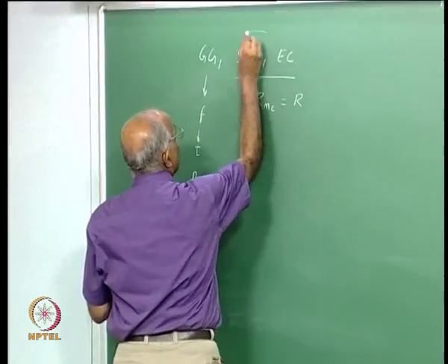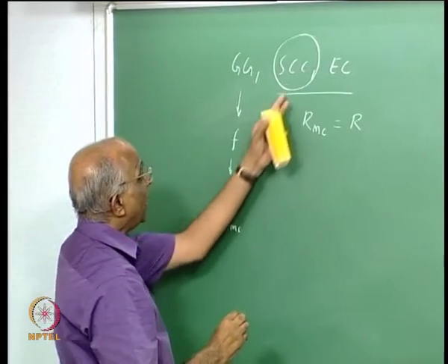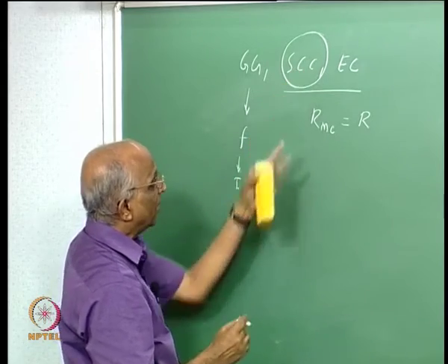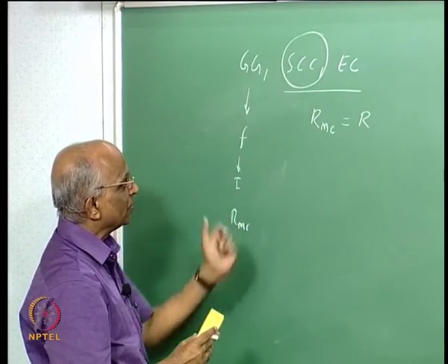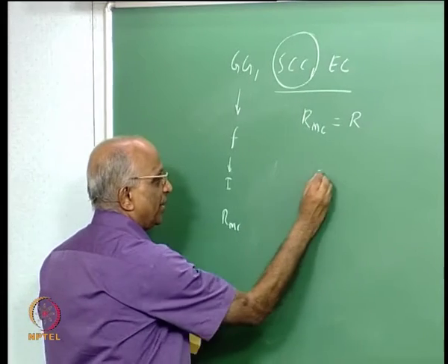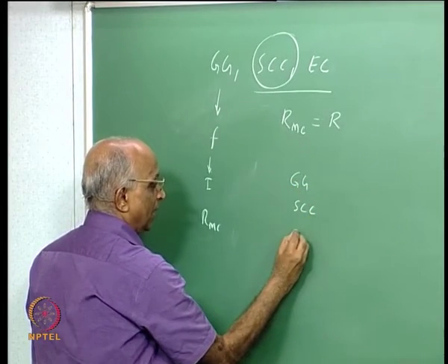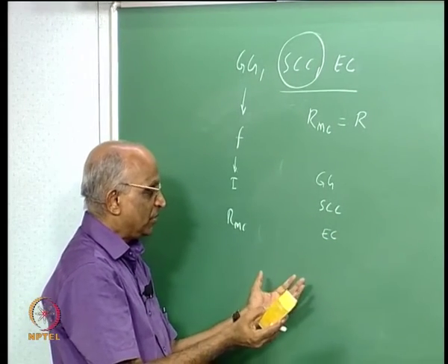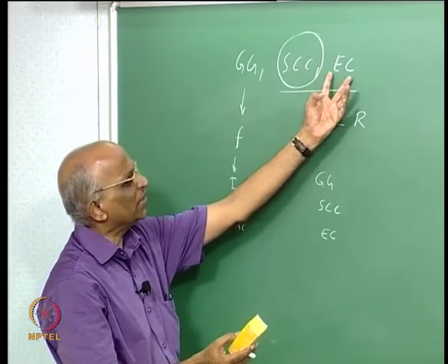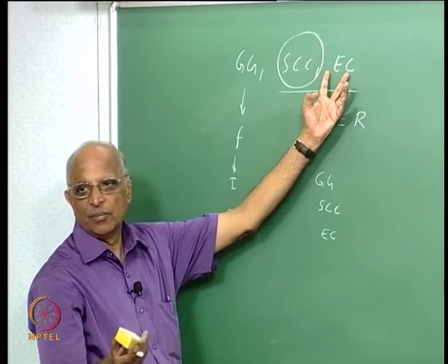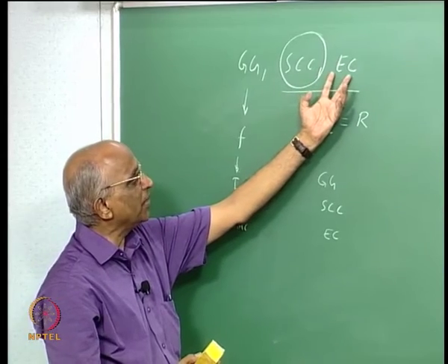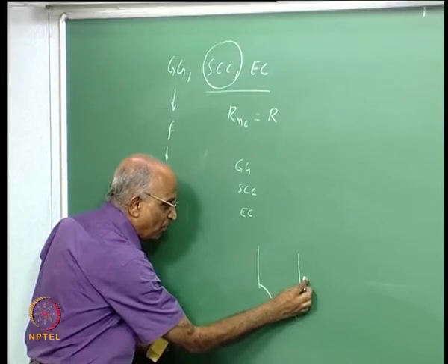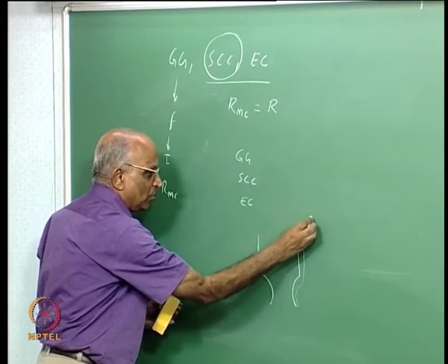For high pressure, the staged combustion cycle is particularly useful because I gain the advantages of high pressure, but we will have to take a look at the design of pumps, which we will do after 2 or 3 classes. I think this is all about the gas generator cycles and the staged combustion cycles, and in the expander cycle we cannot operate at high pressure because we use only a vapor which is generated by heating of the chamber, but this also has some powerful implications. Maybe we will take a look at some examples. Why can we not operate at high pressure in an expander cycle? We are using a chamber which runs hot to be able to form vapor from the gases, and this vapor is used to drive the turbine.